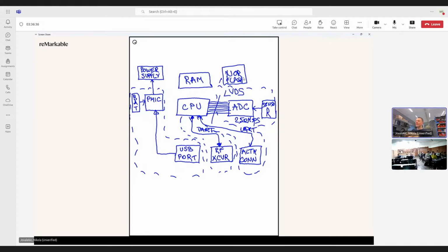Okay, and there is also one specific requirement. We need to have dedicated onboard memory, which will actually store the measurement data. I can put some NOR flash maybe for that. Why is that used? Well, while you are flying with this device, you will try to send your data in real time through the wireless connection. But because it's wireless transmission, it can happen that you lose some packets, and you don't want that, of course. So you are going to do data storage in parallel. You will send the data and store them, send the data and store them, and then you can compare the data when the flight is finished and see if you missed something.